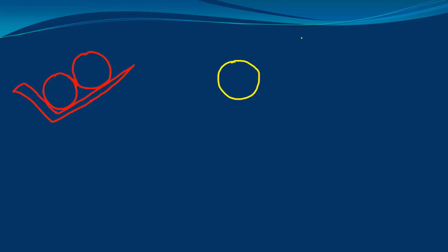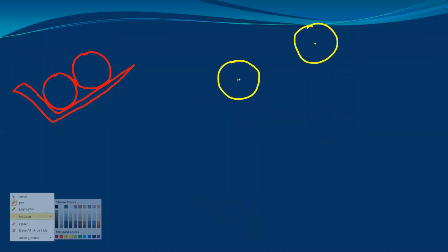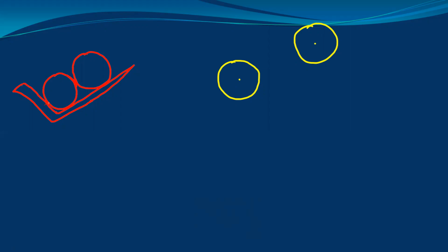Now separate the spheres from each other like this. Now on this sphere, we will show the reactions similar to the last problem. So here we have the first reaction, this is second, and this is the third reaction. So this is the reaction R1. It will pass through the center. Then here we have reaction R2. It will pass through this center. Then we have the weight W.